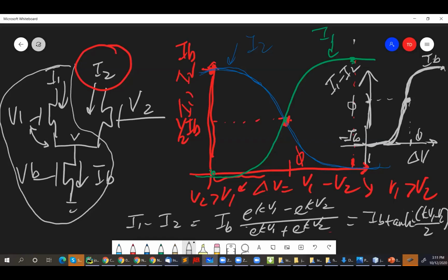So if I say that VGS has to be, say, 0.4 volts for subthreshold operation, can you give me some possible values for V1, V2, and VB? Sorry, VGS off? Yeah, for subthreshold. So I say that in subthreshold, I give one value only.